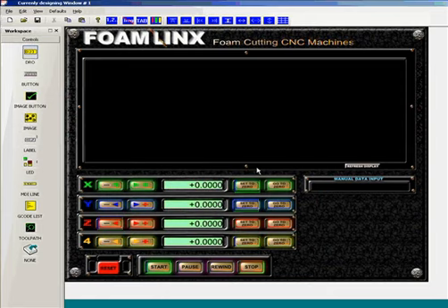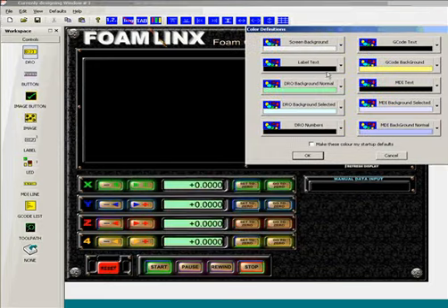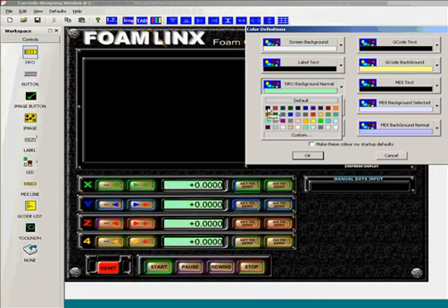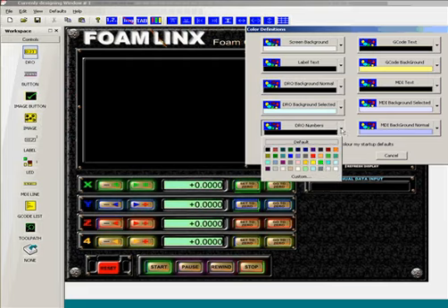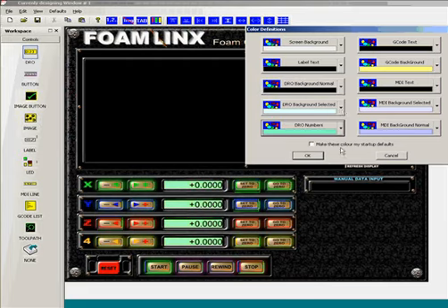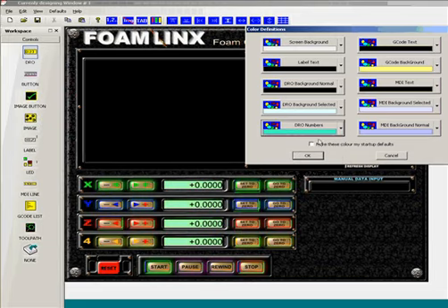Once you've got your digital readouts in position, you can change the background colors and all that to suit your design. If you go up to this color selection icon up here and click it, you'll notice you can change the different colors. So for the dro background, when it's normal and unselected, in this instance we'll make it black. For the dro numbers, obviously they don't want to be black. We'll make them electronic blue. Let's call that electronic blue.